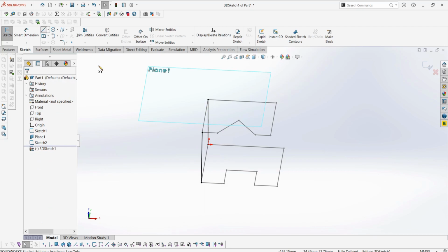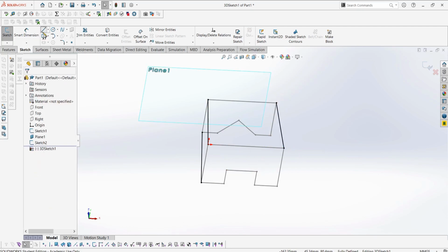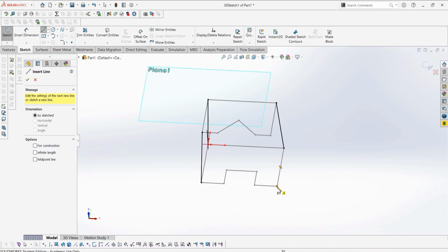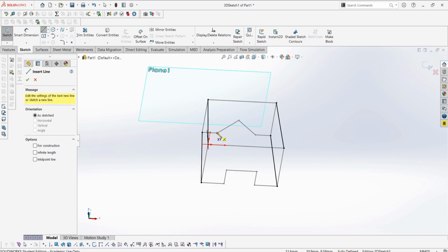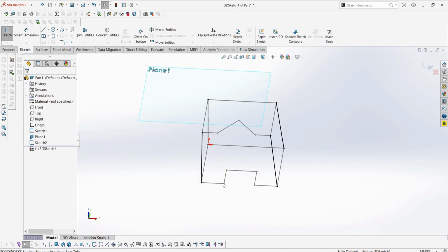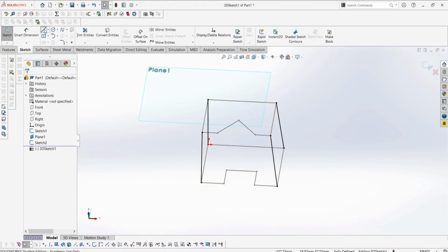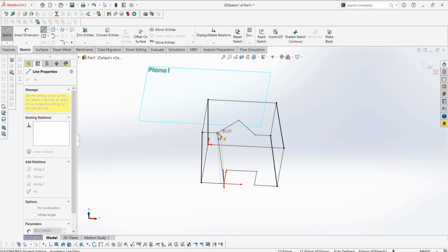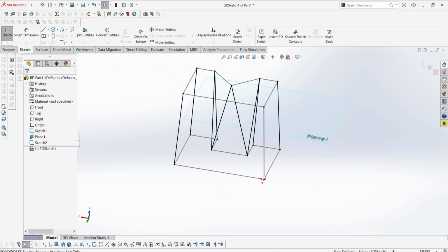And when it comes to making our weldment, that's quite nice because to create a weldment with one group, you can either have all the sketches be parallel or the sketch be continuous. And since it's up, down, up, down, up, down, let's see where it starts. At the bottom and then the top. Okay. So basically, see how I'm just doing this with one line. I'm not changing the start and end. You can make that all one group, which makes it easier and quicker to make the weldment.